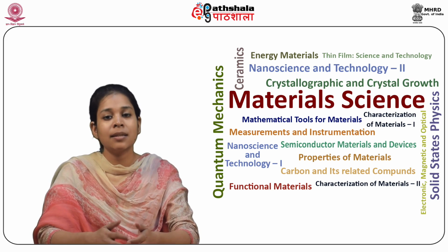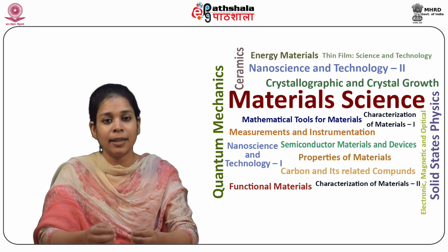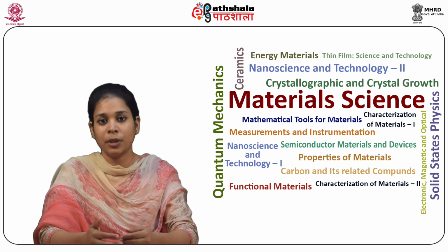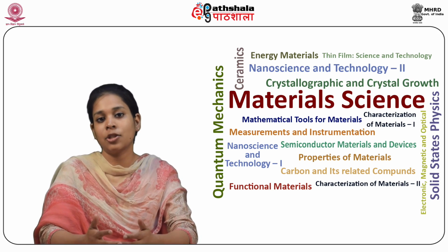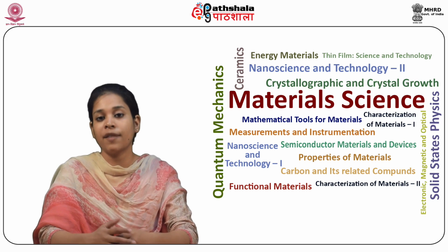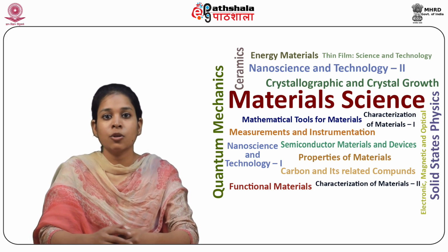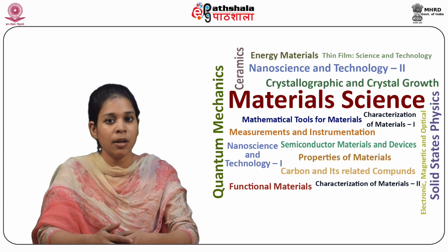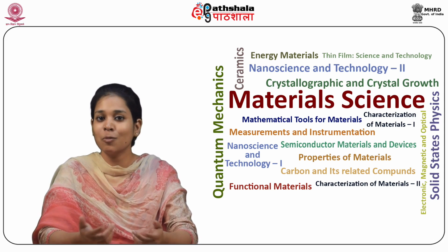Then the piece thus obtained is called a green body. The green body is first dried and then fired to obtain a completely dense structure. So the characteristics of the starting powder have a great influence on the final properties. One of the most important characteristics of ceramic powder is its particle size distribution.